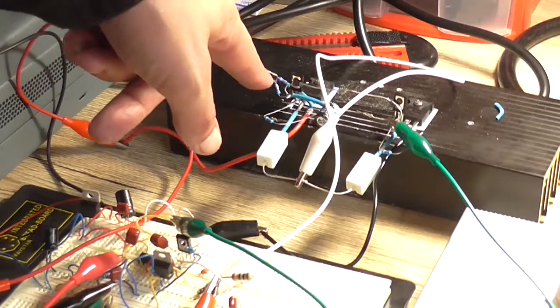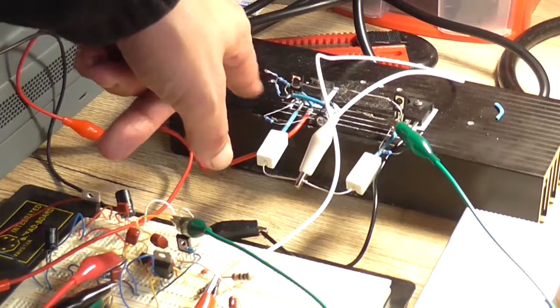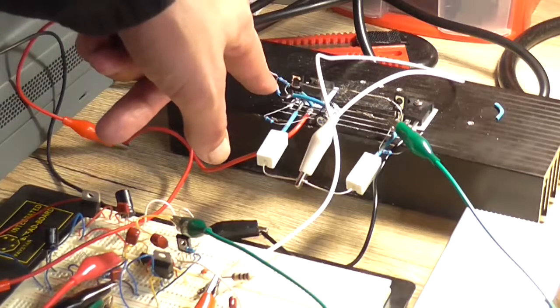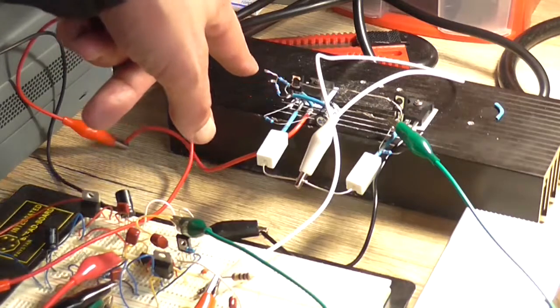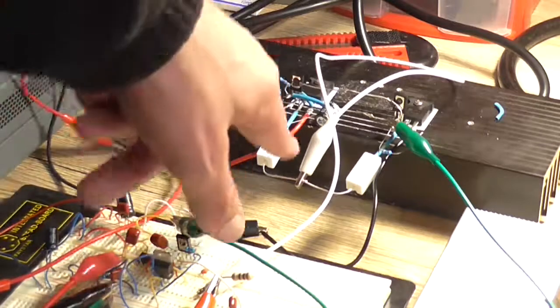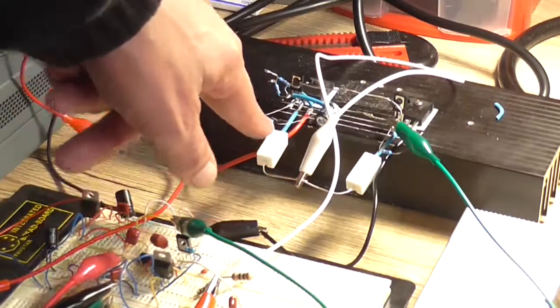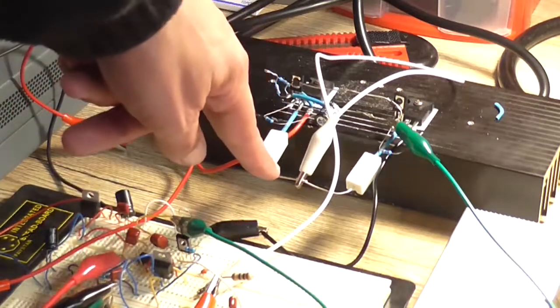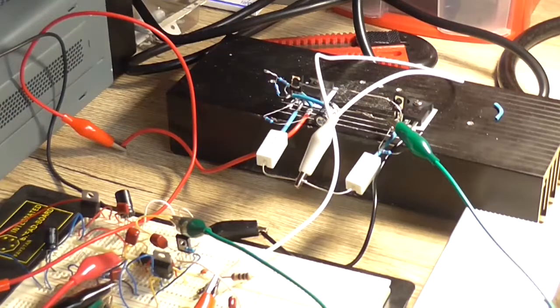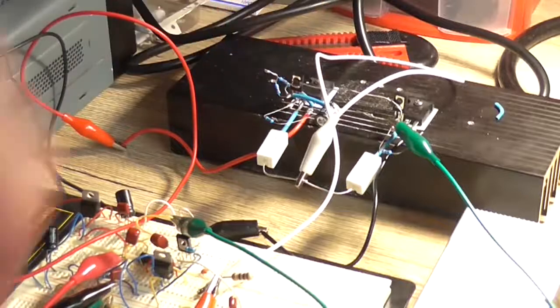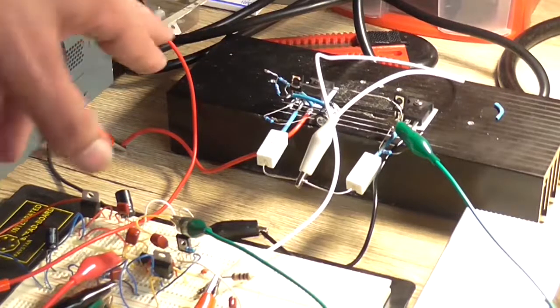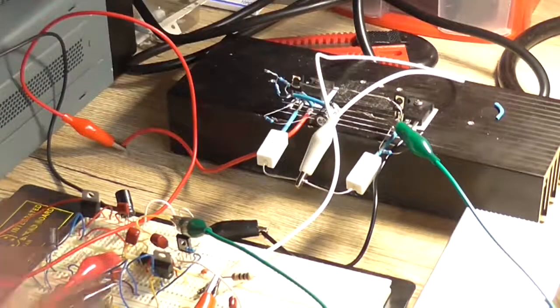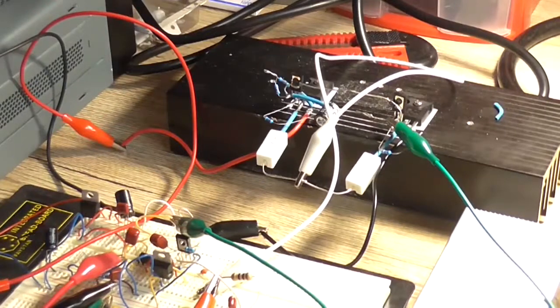So I've actually got two 2.2k resistors in series here, and this join can be connected via a 100 microfarad capacitor back to the output, positive at this junction, negative at the output, to bootstrap the amplifier to give that output stage a constant current source. However, I couldn't see any difference in the results on the output by adding it or not having it.